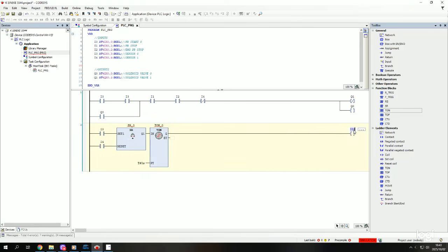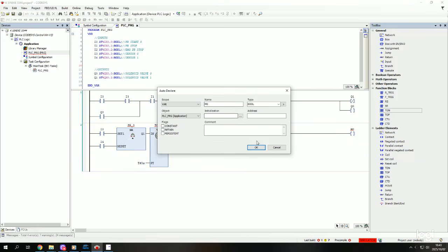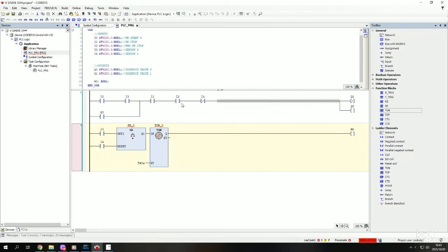And then our output. Usually our output is our solenoid valve, but when we insert our timer, our output becomes a memory. That memory, we say it's M0. That's our first memory, M0. So now we need to change our initial ladder logic diagram, just a small change.